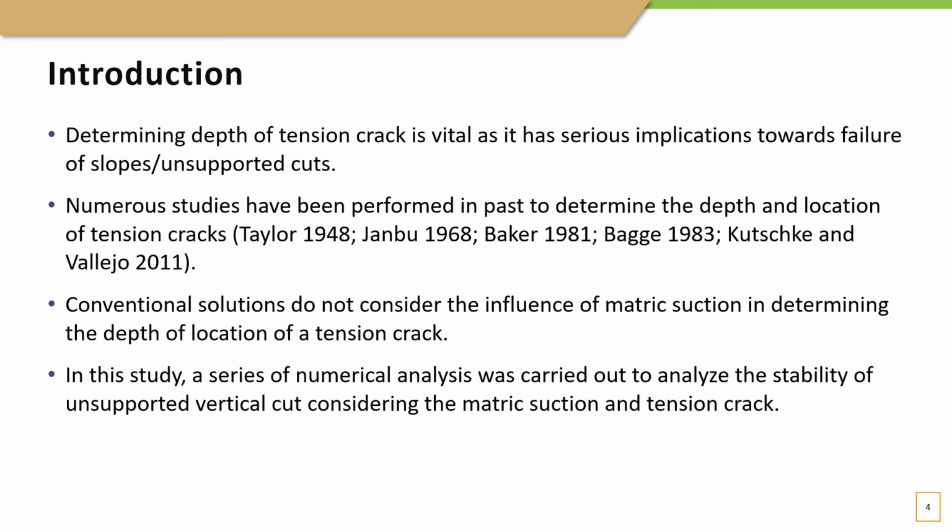Various studies have been performed to determine depth and location of tension crack. However, these studies are applicable only for saturated and homogeneous conditions, which often isn't the case in the field. In this study, a series of numerical analyses were carried out to analyze the stability of unsupported vertical cut considering the influence of matrix suction and tension crack.